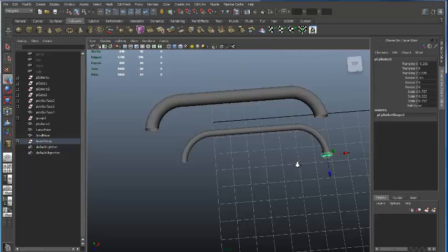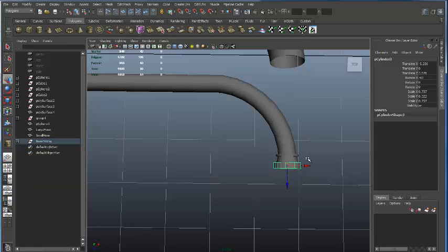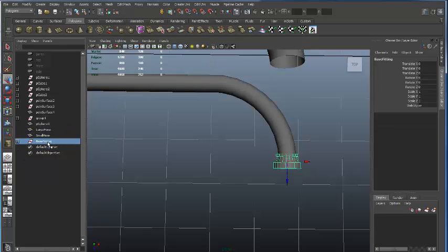Okay. So I'm now going to take that piece here. Uh-oh, what's happening? When I select it, it's not selecting the whole entire object. Why? Because I'm on independent selection mode. If I go back to the hierarchy selection right here and select that, come back and touch it, it'll select all of it because I already have a grouping. The other thing I could have done is come in here inside the outliner and touch the grouping itself, and it would have selected the object.